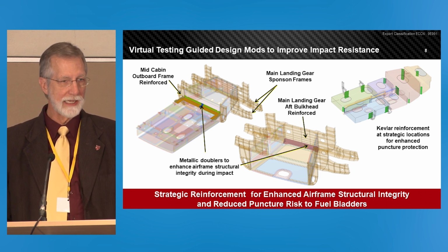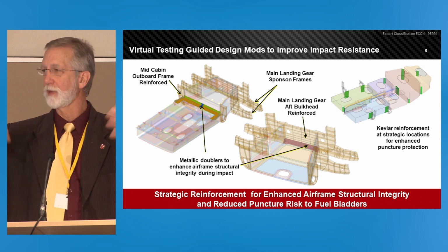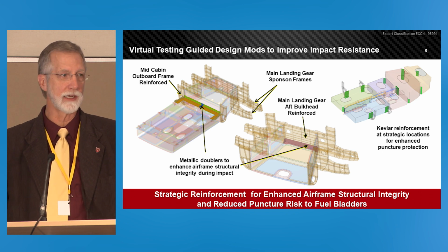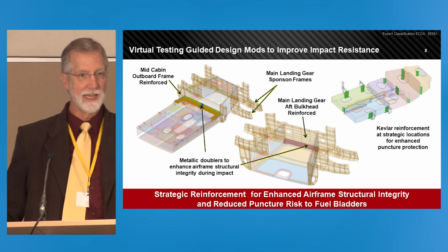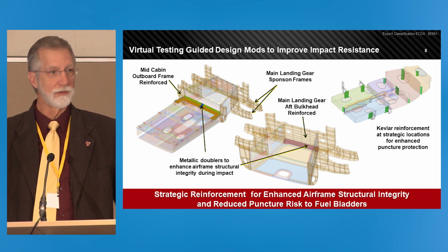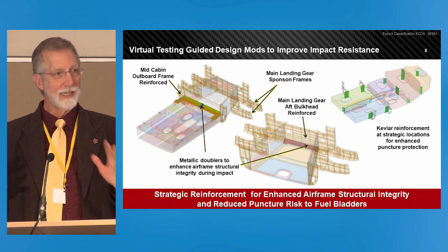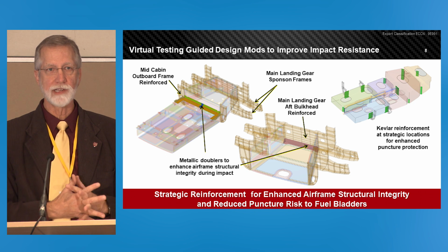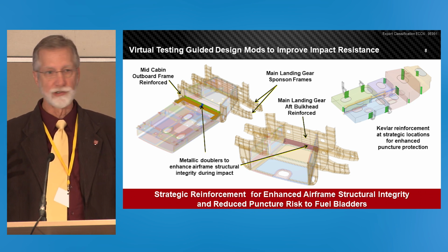The pressures you're looking at are not as low as 100 PSI. You're talking about like 500 PSI type pulses on the bottom of the tank. Well, most of the designs are not going to be sized for 500 PSI static, nor should they be, because you won't be able to fly a helicopter. It'd be way too heavy, right? So you've got to run through this in a hydrodynamic type of environment where you size the pulse and the energy, and remember that going plastic is your friend.